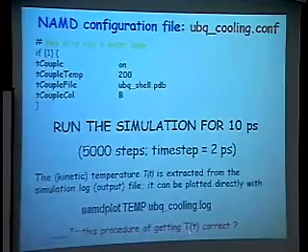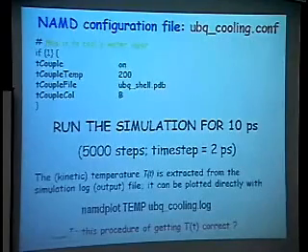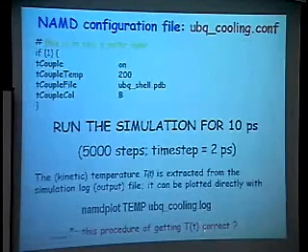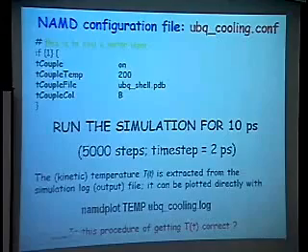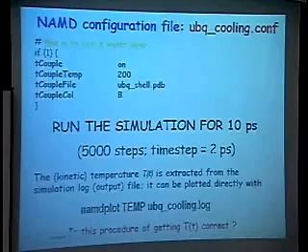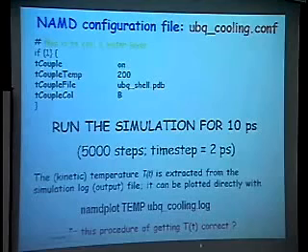Namely, you know that the temperature you're referring to here is the kinetic temperature of an inner layer. The question is, the outer layer, is it calculated or is it taken into account or not when you do the calculation? How can you figure this out? Only if you know how NAMD works. And my understanding is that actually the outer layer is not included in this calculation, because that is the heat bath. The heat bath stays at 200 K, so it makes no point to add it into the kinetic temperature. So when NAMD calculates for you the kinetic temperature, it calculates only the atoms which are subject to the usual Newton dynamics.